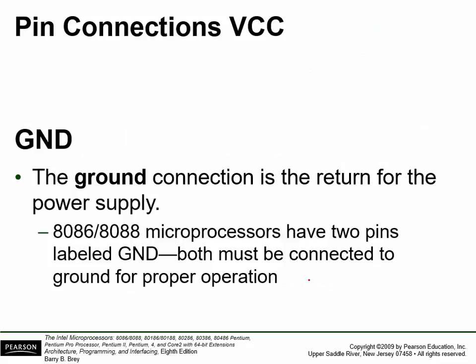Everything must be grounded. Every device in a hardware system must share the same ground. If I connect two pieces of equipment that are physically separated from each other, they must share a ground between them. Example: a USB thumb drive you plug into your PC. One of the pins on that is a ground. They don't necessarily have to share the same power.